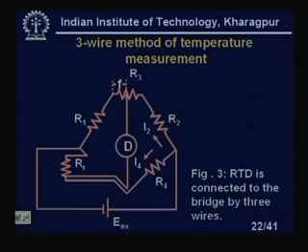So, this contact resistance is no more in the bridge circuit. Whatever bridge balance equation we write will be absolutely correct, and the contact resistance will be in the detector circuit. So, it will make the detector more sensitive or less sensitive, it does not matter, it is nowhere coming into the picture. So, I am denoting some current because we have to calculate something.